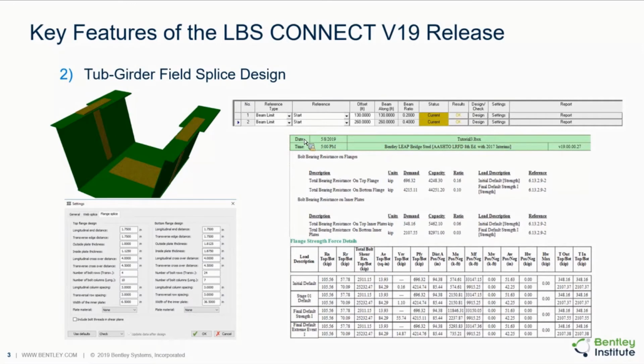And we are running many different checks for the field splice design. This is just a very small example of how the reports will look. Here we show the bolt bearing resistance and bolt bearing resistance on inner plates and flanges, as well as the flange strength force detail table. Again, this is a result of the new LRFD 8 application.